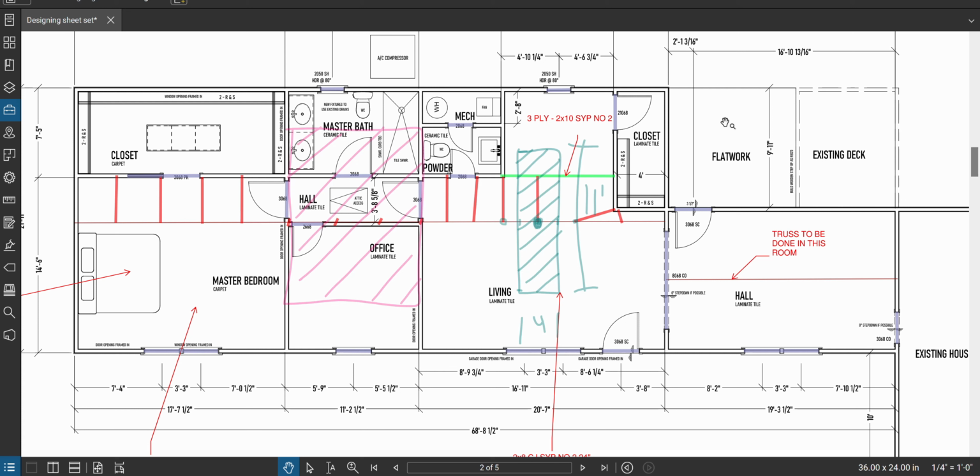If I did have that, I would also want to know what post cap type I'm going to use, and what metal hardware is going to allow me to connect that to the rest of my structure. I'd want to find that. Built up posts go under the beams.